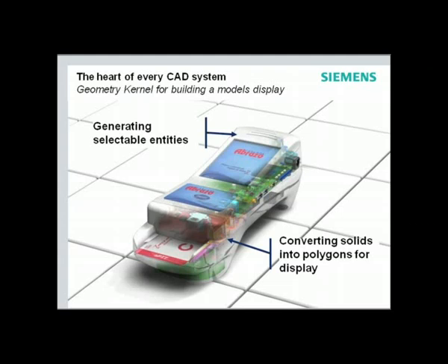Computer graphics cards, whether you have an NVIDIA or an ATI or whatever, don't understand anything but triangles. They can't display B-spline surfaces. They can't display cylinders. They can't display spheres. They display triangles. So what the CAD system does is it takes whatever it's got, in this case some B-spline surfaces representing the casing and the rounds and so on, and breaks those down into a triangle mesh.